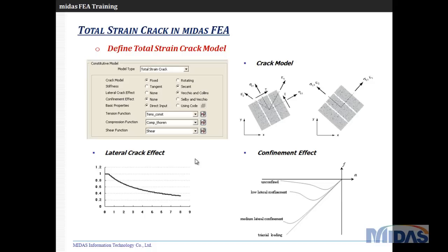If the tensile stress reaches a certain limit, which we will be providing in this model, the additional deformation will localize within a region called the fracture process zone. After the tensile limit is reached, the stress in that fracture zone decreases as the strain increases. When the tensile stress approaches 0, a macro crack will be formed in the fracture zone. This phenomenon is known as tension softening, and we can consider it